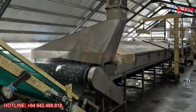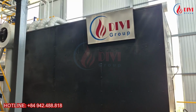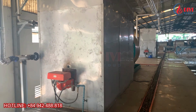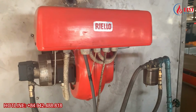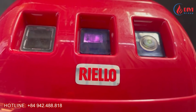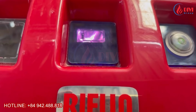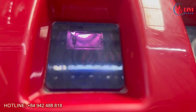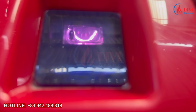Steam-based drying is also an effective way for factories to reduce production costs. In the past, many conventional drying systems used diesel, LPG, or natural gas burners to heat air directly. The hot combustion gases were mixed with air and then blown directly into the drying chamber. The biggest drawback of this approach is its high fuel cost. In addition, direct contact between combustion gases and the product can affect its color, odor, cleanliness, and overall quality.